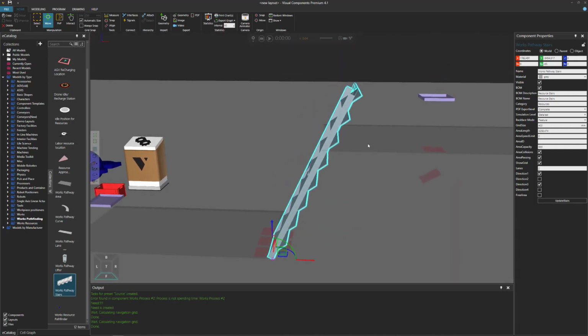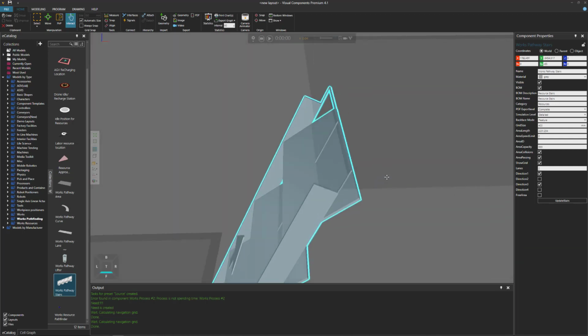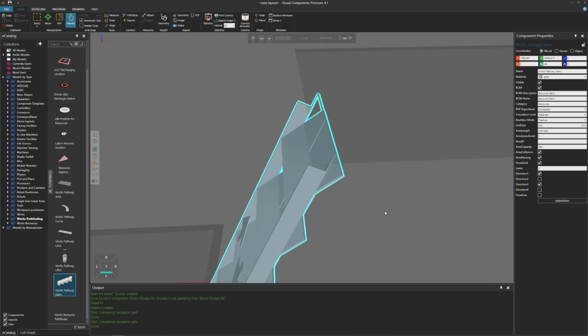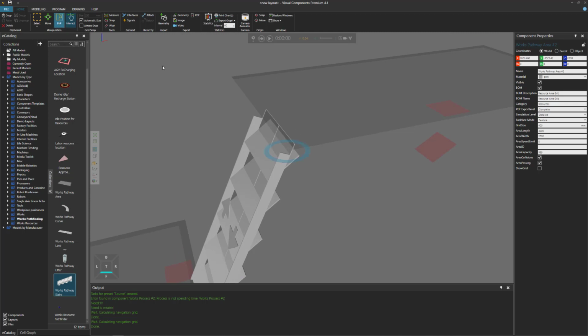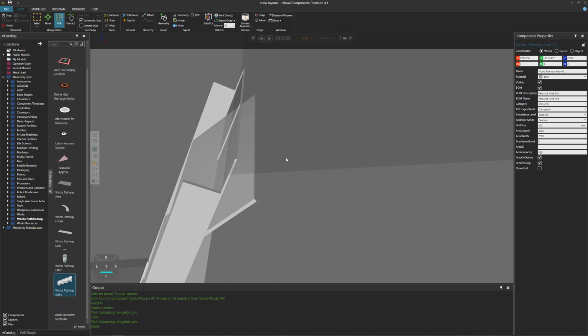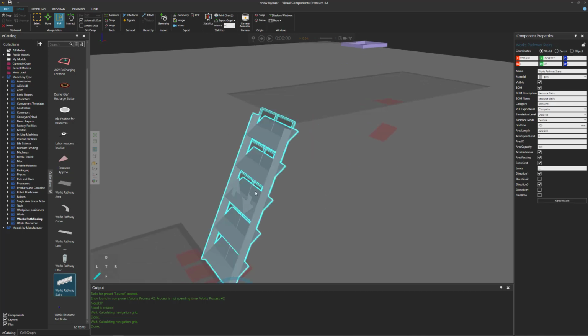That's fine. But now the stairs are too long, so I'll interact with the stairs and make them shorter. And we just want them to intersect the geometry here. So right about there. But then this area needs to be moved a bit, so let's move it over here, and just make sure they still intersect or touch. And yeah, that's okay. See if it works. And remember, we need to update our stairs so each step is level. So let's update the stairs.